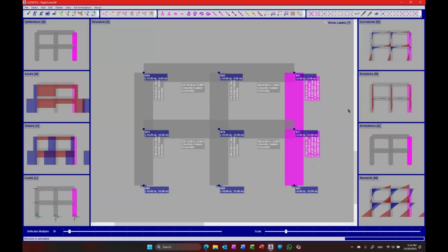So this column looks okay, but these beams look like half of them are in the second floor or the third floor, and half of them on the second floor, and same thing over here. So they don't really simulate a true to life behavior, because it's more common to have the beams sort of defined at the top of their surface, right, at the floor level.